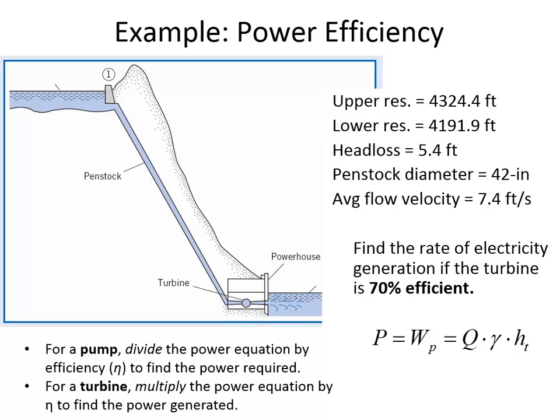There are dams along the Mississippi River, for example. If you think about hydropower, but what's the problem? If this is the power equation, what's the problem in trying to harness electricity from the Mississippi River? The problem is that it's a very flat slope river, and so you can put in a little dam, but you're not going to have much of an elevation difference.